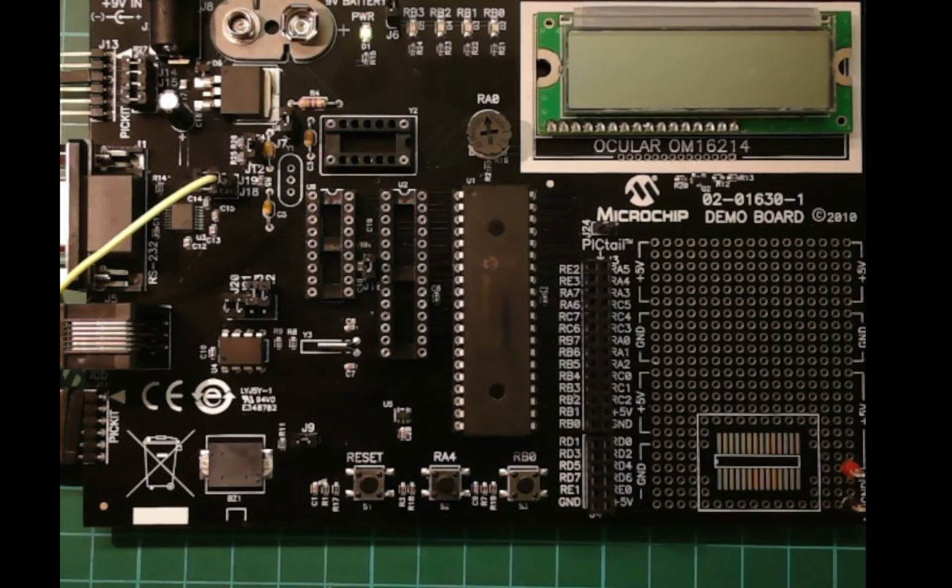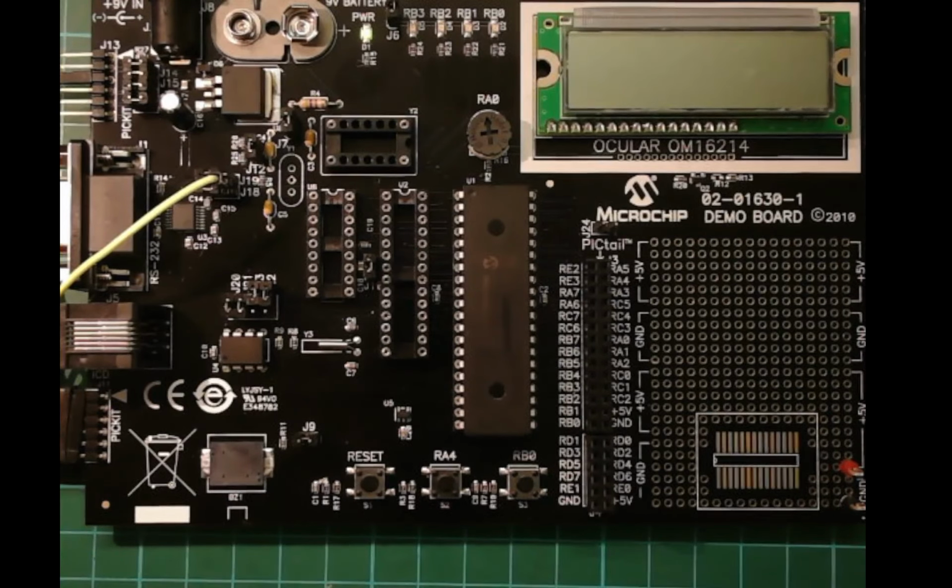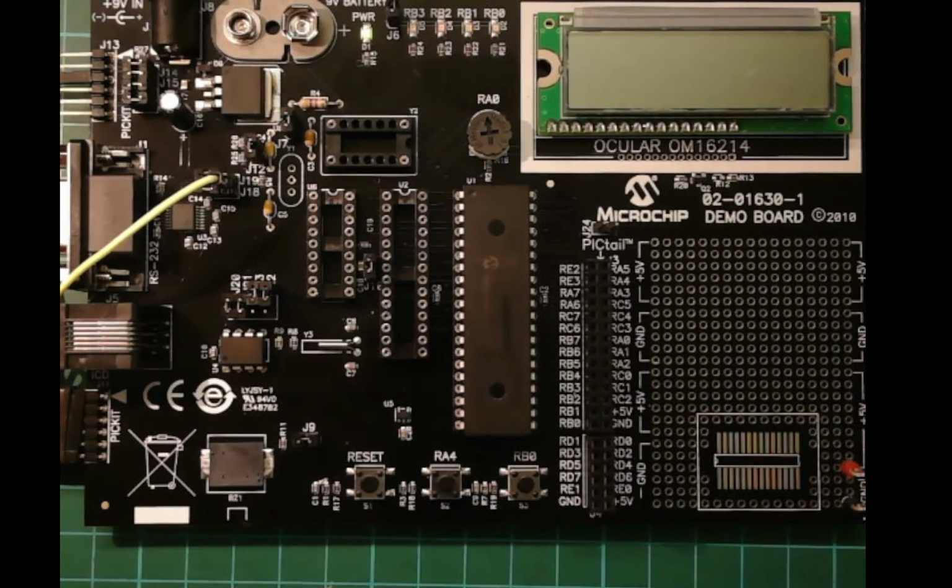So what have I got hooked up? Well, I've got the SDA on port C.4 and the clock SCK on port C.3. I can't change those. This is a legacy chip. With the newer chips, I can change where I put those, but on here, it's locked to those ports, so I can't put them anywhere else. If I'm using the hardware I2C routines, I have to pick these ports. I have no other choice.